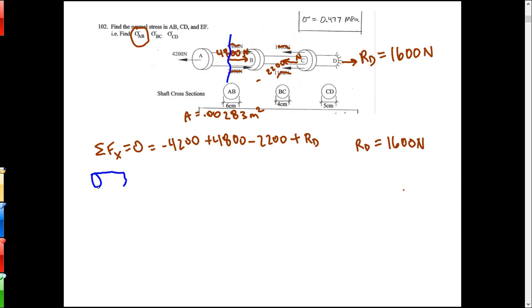When I take a free body diagram, I use one whole side or the other. My goal here is to find the internal forces. So there's the load anywhere between A and B. Now I could have used the other side as well. It'll be more work because there's more stuff on the right, but I could use that as well.